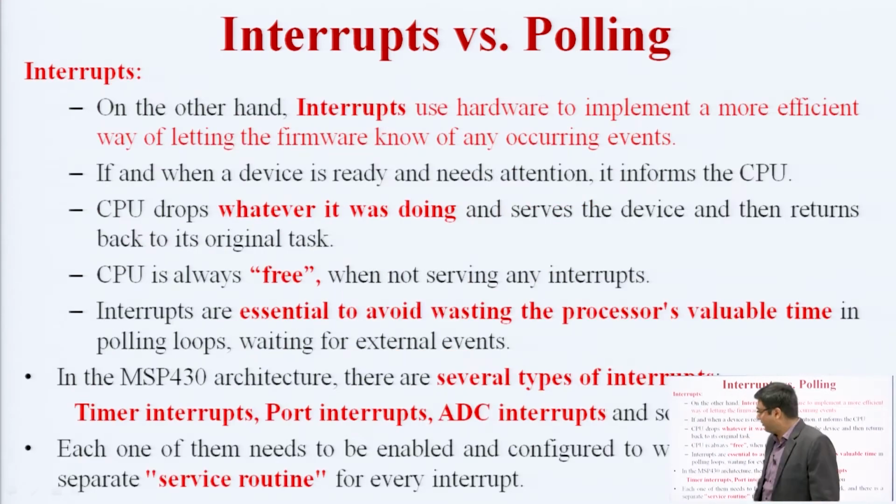But in the case of interrupts, we are not constantly checking the input output pins. An interrupt will occur at any time during the program. The CPU will sit in sleep mode, and whenever any interrupt occurs, it will go into active mode. So it does not continuously check the data. In polling we constantly check the data, but in an interrupt, when it occurs, the microcontroller will go to service that particular interrupt.